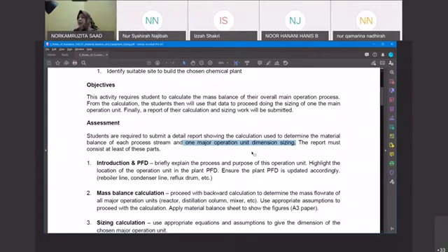Okay, so normally we're going to have maybe 70%, 80%, 90%. So it must be rational, and you must have a justification of having that particular percentage of recovery of your product. Okay, so when you have that, you're going to keep that in your mind, that whatever it is, what you can control is only the inlet stream. Okay, or maybe you can control the retention time that you have the materials in the column.